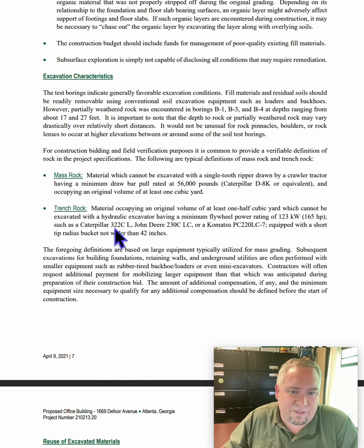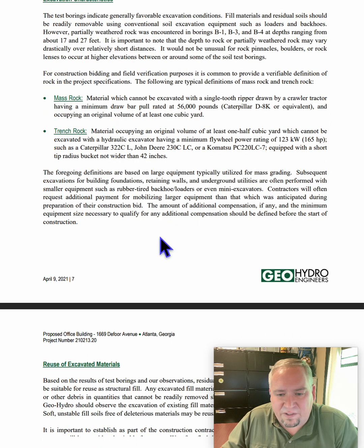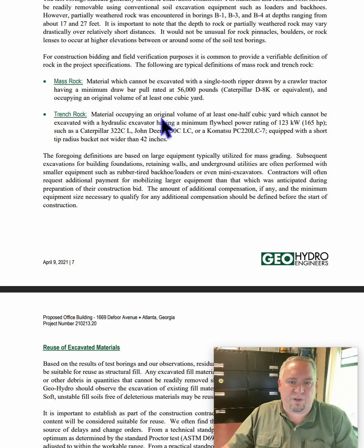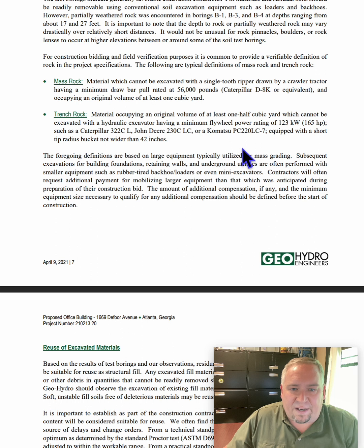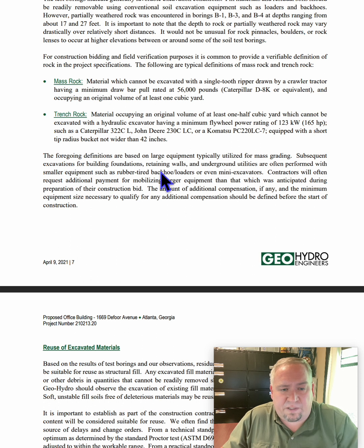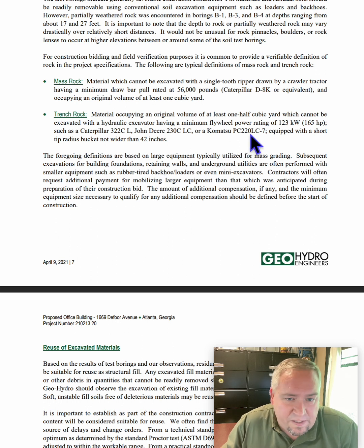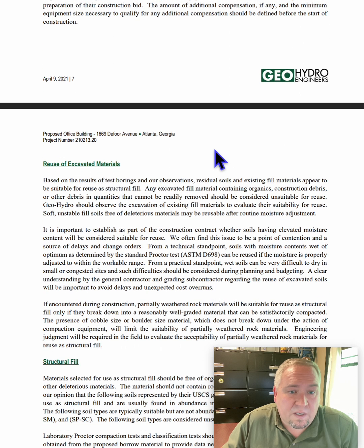So the horsepowers and bucket widths, they've updated those. So you need to know your numbers on what a Deere 230 is and about what it can do, or a PC 220 Komatsu, when we're bidding, that way you can get the general expectations there. Most of these PC 220s come with a 42-inch bucket, or in the 36, 42. So they're within range, and that's pretty standard equipment.